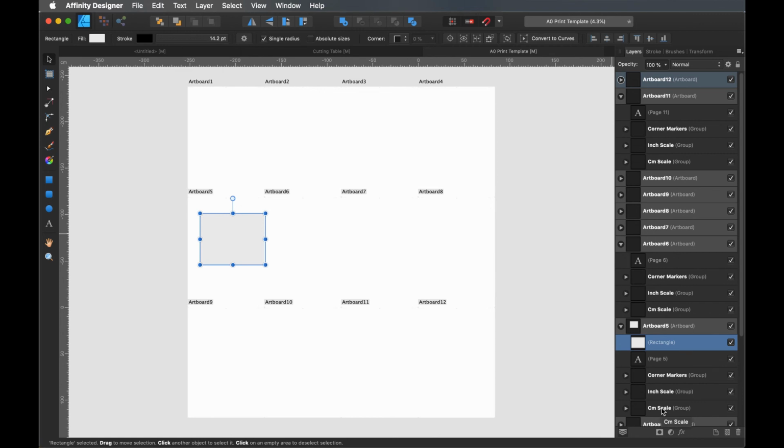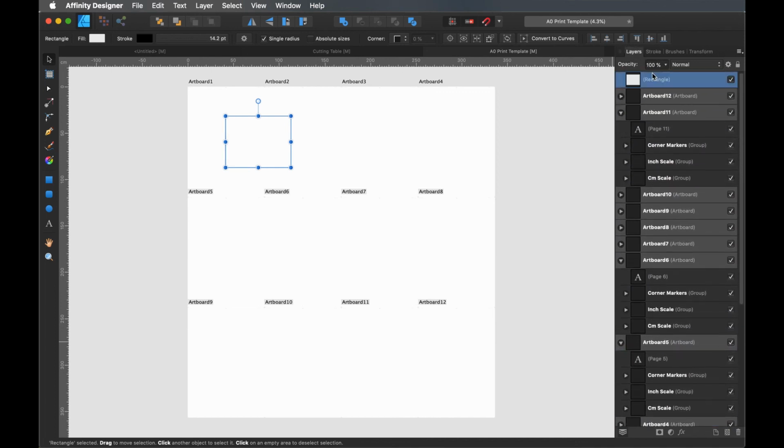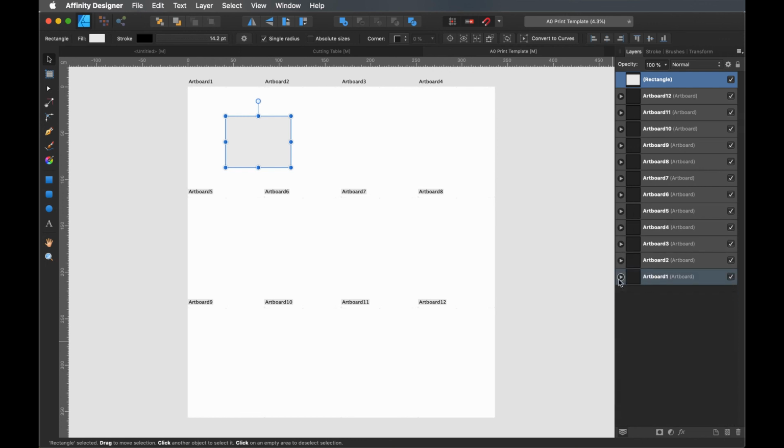so it's moving around all over the place here. The reason for this is that the way Designer works, particularly with artboards, is that wherever you're working over, that item then becomes a child of the artboard that you're working over. There isn't an option at the moment to deselect this and allow it to work over any artboard. So it is worth bearing in mind, particularly if you have groups of big objects, that if they start disappearing like this, you haven't lost half of your pattern or anything like that. It's just hidden under the artboard. So you will then need to grab it and drag it all the way to the top for it to appear over both. It's a bit annoying, but unfortunately that is how artboards are set up at the moment. There isn't really an easy way around that.